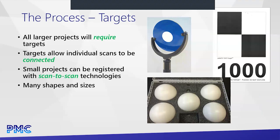As projects get larger, certainly anything over, let's say, 100,000 square feet, you should expect to see some targets put up around the space, and they can vary from paper checkerboards that maybe you've seen around to spheres and a number of other things that can be temporarily put into the space. On some jobs, we also install permanent benchmarks. These would be for ongoing scanning, typically either an active construction or a manufacturing site. But most of the time, you're either going to see no targeting at all, or you're going to see temporary targets put up and taken down.